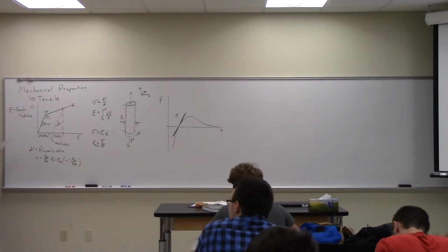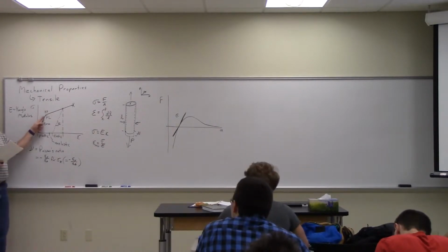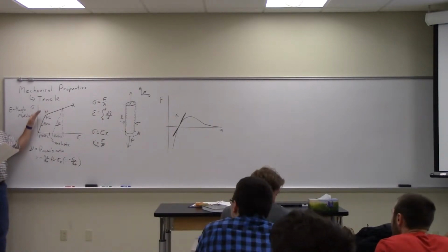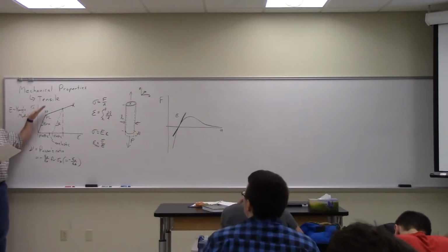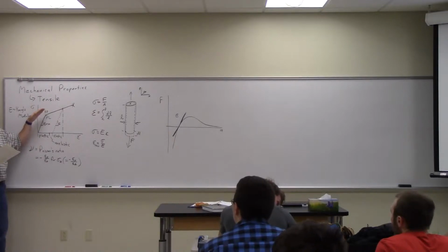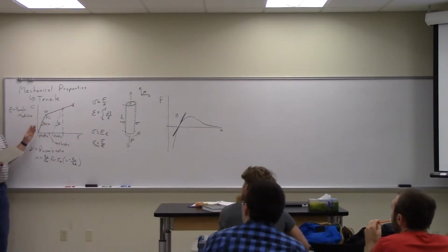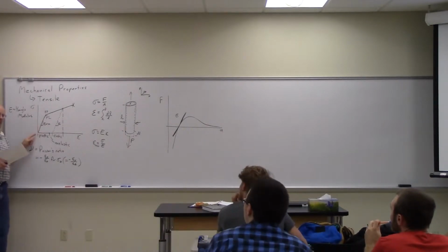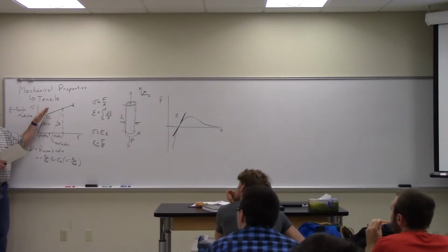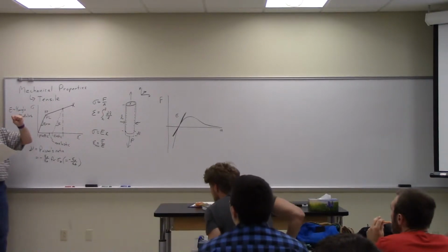Okay, so the yield point is there. The convention for defining it, because it's really hard to define if there's some nonlinear elasticity here, it's really hard to define the point where it actually begins to become permanent deformation. I mean, you have to load it up and then let it go and remeasure. And load it up to a slightly higher load and then unload to remeasure and so on. You have to just keep going up and down the curve until you finally get to the point where, okay, it's a micron longer than it was before, I've had permanent deformation.